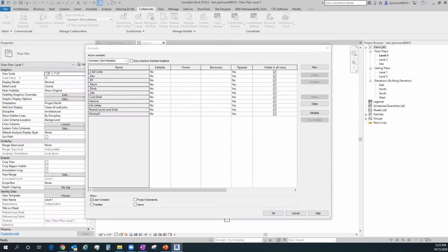It's not an active section that's on a sheet. I could look into a schedule and validate whether they're on a sheet or not, or I could use my project browser to show me everything not on sheets with filters. And then if I just look at sections, 3D views, things like that that are basically unnamed, I can wipe all those out. Usually that reduces the file size by about 1/4 to 1/3 of a meg per section. So if you've got 300 sections in there, you're probably going to get back 70 megs of your file size, which makes everything open and sync faster, right?